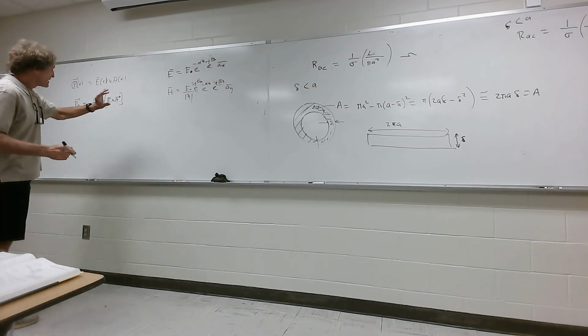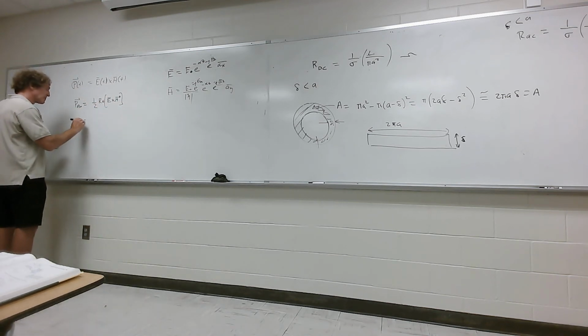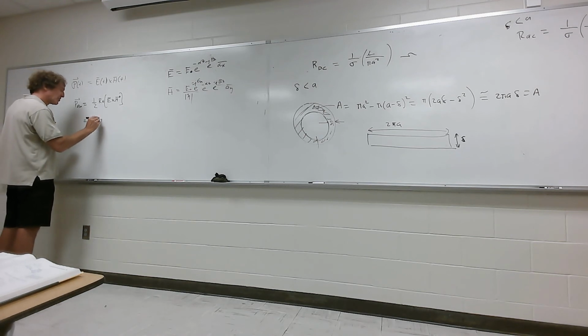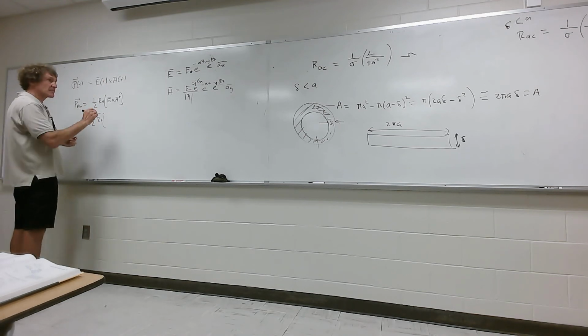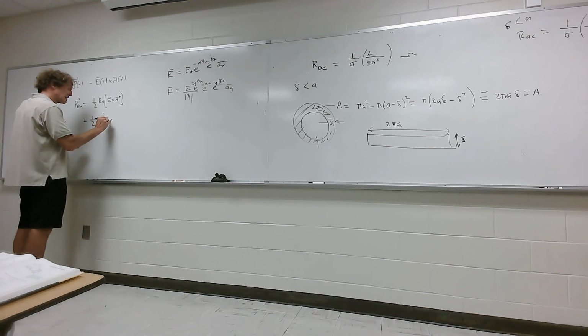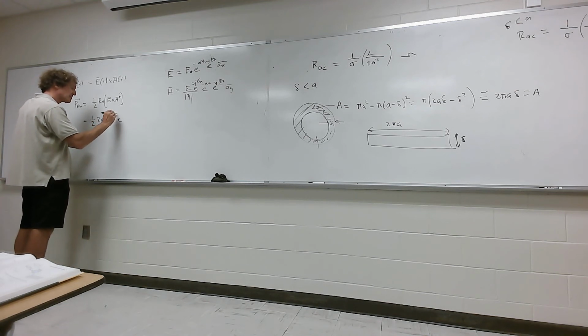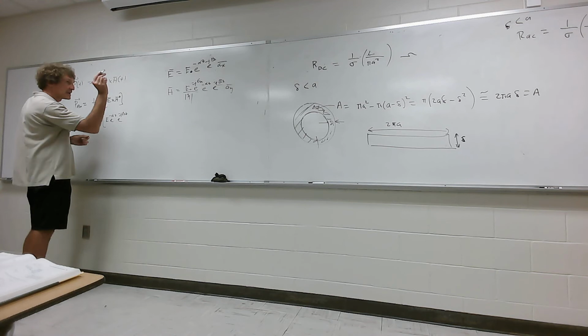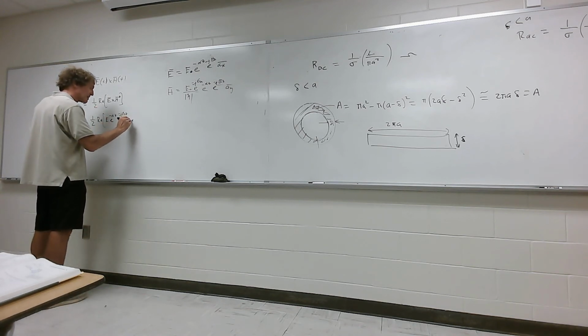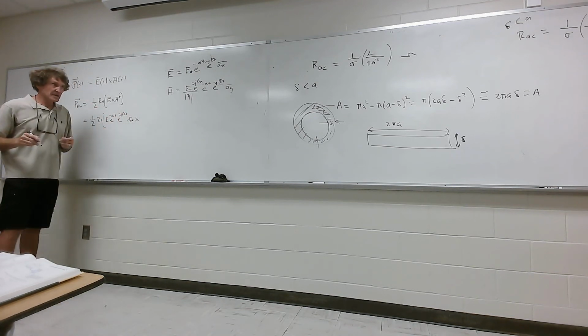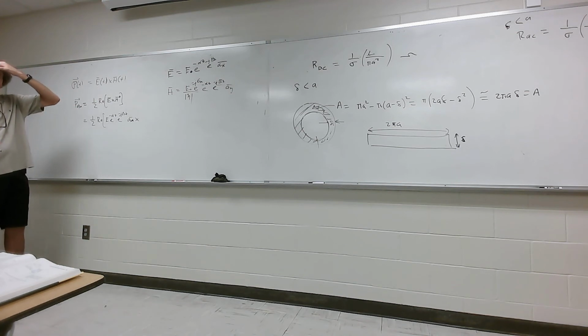Now when I take a look at this, and I apply this magnetic field into this equation, I end up getting 1/2 the real part of E, well there's E right there, so it's E times e to the minus alpha z, e to the minus j beta z, in the AX direction. It's crossed into the H field, but it's the H field conjugated.